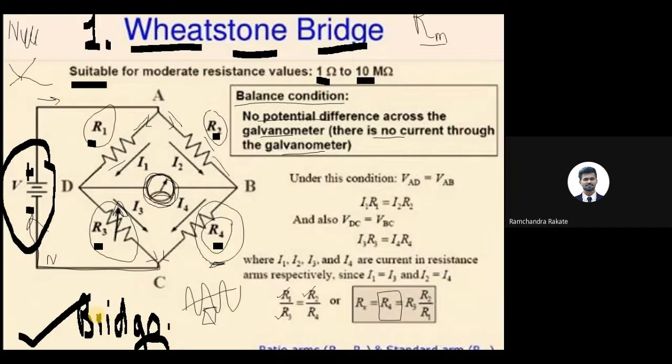The live path is there, the return path is there, so there is a complete circuit. If there is no return path, there is a chance of leakage current, and the person operating that appliance will observe an electric shock. So that's why phase and neutral, that is the return path, are there.